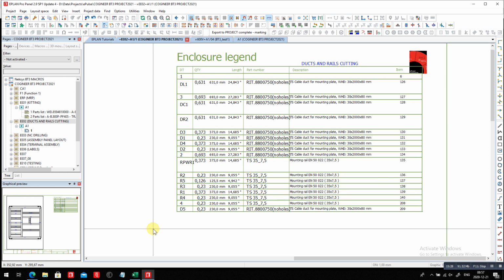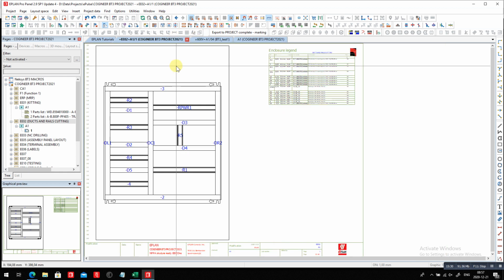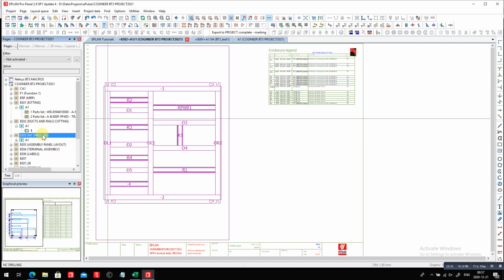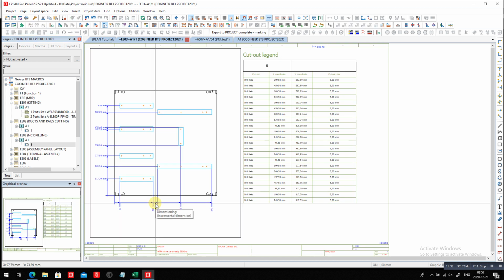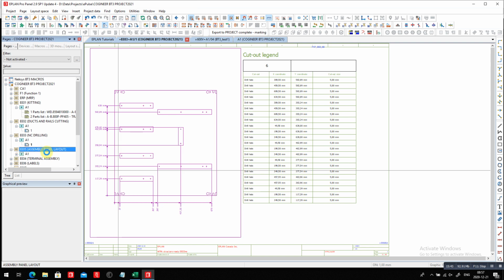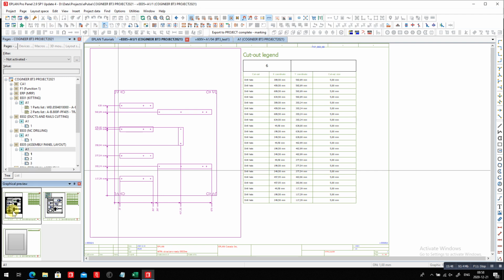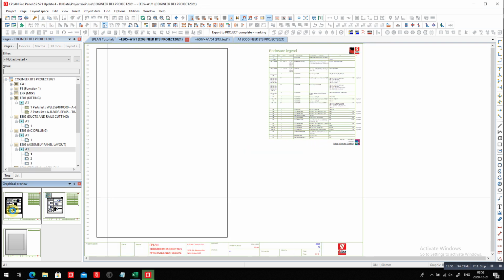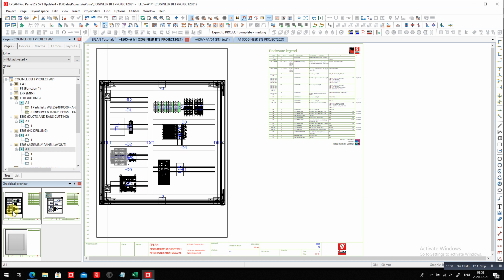Then comes the step of preparing the backplate with holes. These are all the holes we need for the DIN rails. If I go one step further, I now have another report that shows the assembled components on the backplate. Now, of course, when I look at this, there are different ways to view it. This is a nice, very honest 3D picture, but the data is hard to read. So I change it a little bit. We have different views. This is actually my preferred view, where I can read the different device tags.